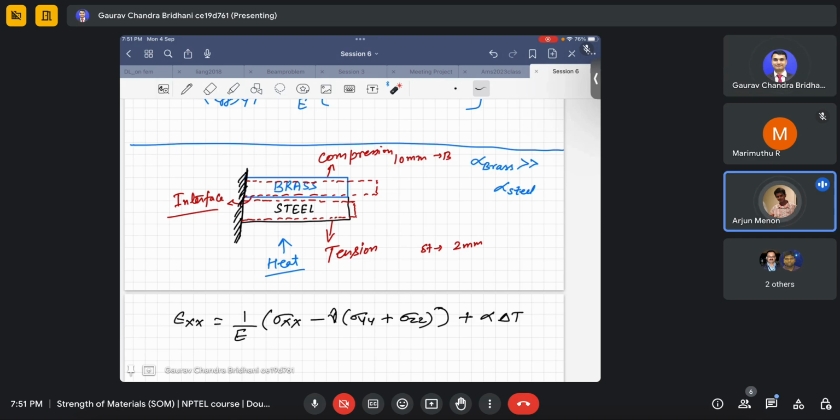Actually, it is still not a correct way to say the thermal strain will be same. The best way is to say total strain will be same. You can't say thermal, because suppose in the final the total extension of both bars is 3 mm. Now the extension of 3 mm won't ensure that there is no thermal stress. It will ensure there is a thermal stress, so you are going beyond the value of 3 mm. So basically you will be saying that the total extension should be same, be it without thermal strain or with thermal strain.